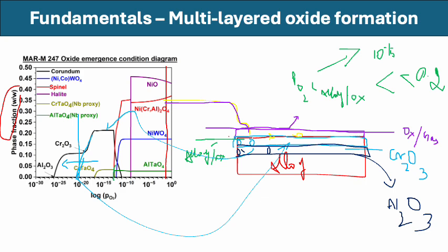And sometimes internal oxidation can also take place. Sometimes if there is not enough aluminium, the partial pressure gradient from the initial surface will be steeper. So up to a point where I am above alumina formation depth, I can even precipitate out discrete alumina particles. That is detrimental. So let's say this is the alloy interface. I am also having some nucleation, but the growth and the aluminum content is not that high, but oxygen still has access to this